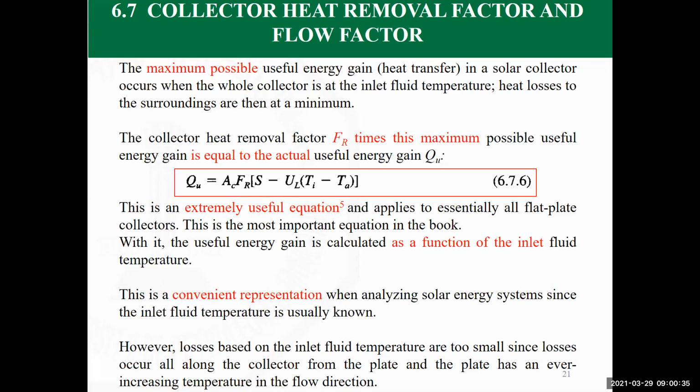So this is an extremely useful equation that applies to all flat plate collectors. And actually, as you can see here, it looks like the most important equation in the book, because this is going to take us, practically speaking, to linking what we see here with the characteristic equation of the energy gain or the efficiency of a flat plate collector. This is the basis on which the selection of collectors or the testing of collectors is done.